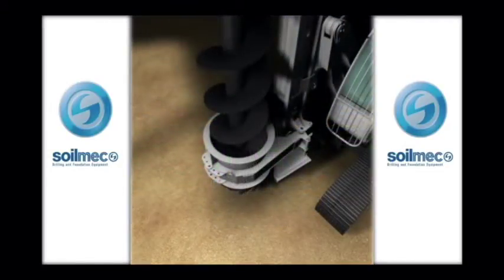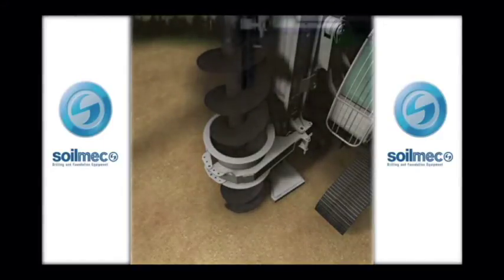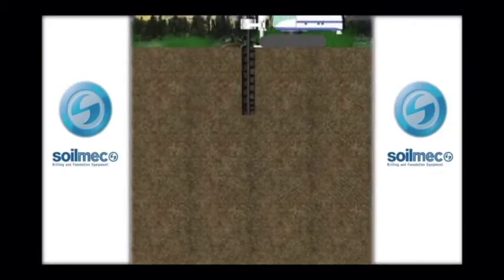This means more concrete needed to be cast, but also means that the foundation will be constructed safely without disturbing the tunnels. They use a technique in casting this pile called the continuous flight auger, which is basically a machine that bores the ground to the required depths and pours concrete in place while going out. This will avoid the potential need to bore and sleeve each pile, reducing the needed time and cost for this operation.